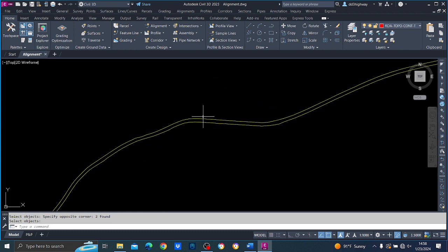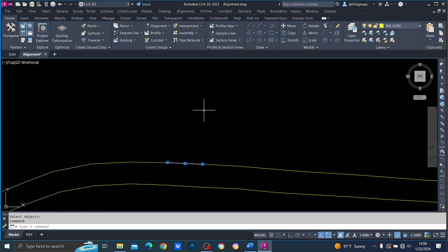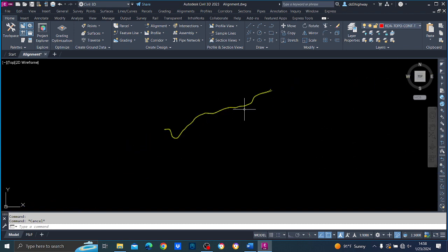Now if you select this one, you see it is a segment, it's not a polyline. Again, now I have to make them polylines. How? There is a method PE, that is pedit or polyline edit. Before that you have to flatten them, bring them into the zero plane. For that you enter flatten, select objects, select everything, press enter.